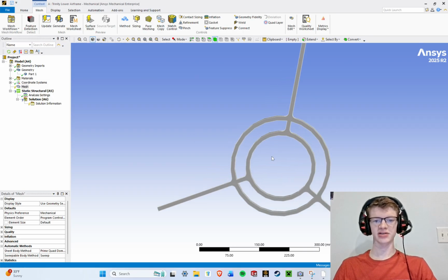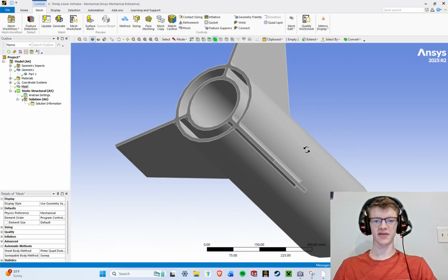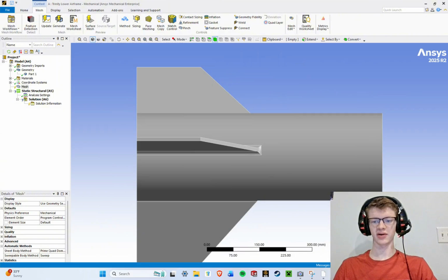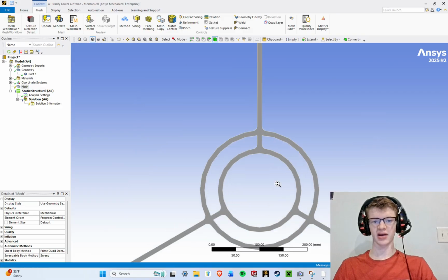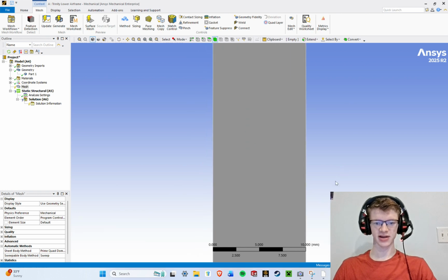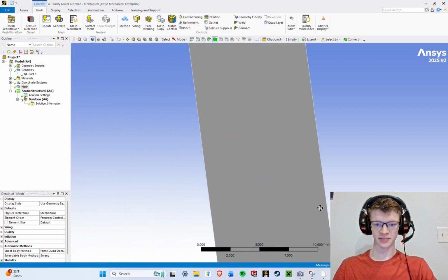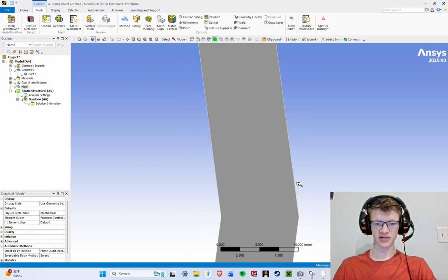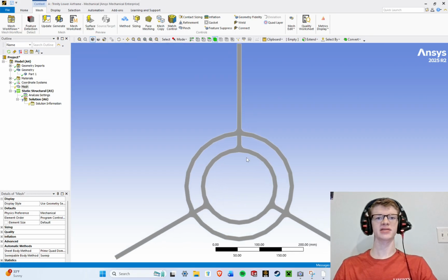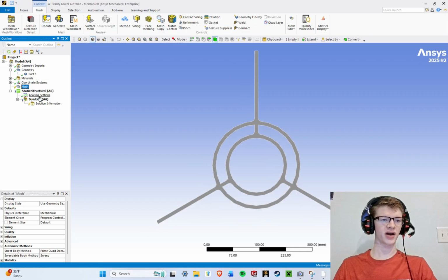I made this geometry so that each wall is 10 millimeters thick because I didn't want it to require a ton of tiny little particles, tiny little elements that would require way too much processing power. And you can see that using the measurement display right here. It's 10 millimeters wide. And if we go to the side of this, we can see it is about 10 millimeters wide as well. So since we want two elements across the thickness of any given wall when we're using Ansys simulations, we would want a 5 millimeter mesh.